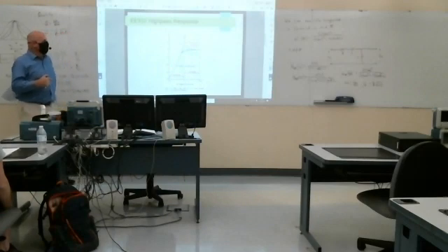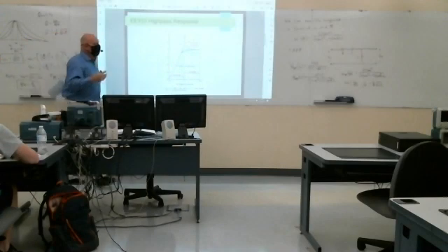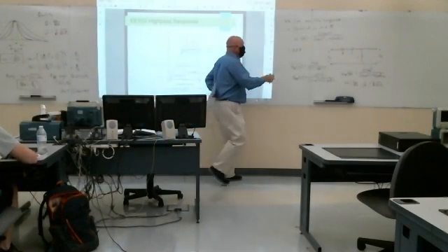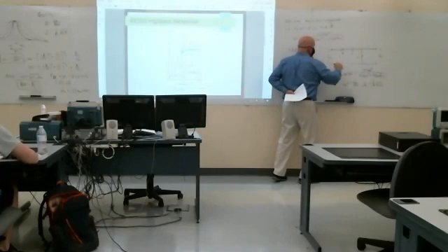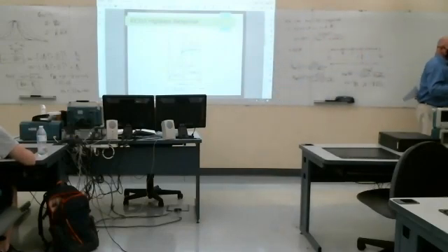Usually these second order filters are components of higher order filters. So we can get really nice responses with maybe 4th order, 6th order, 8th order filters. But we know, if I have an 8th order numerator and denominator here, I can always factor that into 1st order and 2nd order terms.